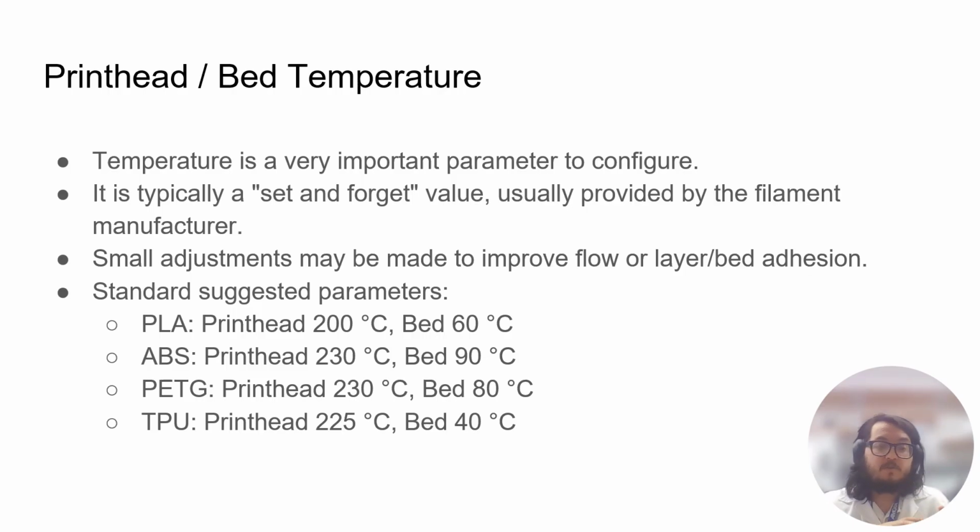The reason why we use those temperatures is that those are the temperatures where some of the amorphous polymers really are in this more flowable state. The more crystalline polymers are in this melt state, so the melting temperature. For the print bed temperature, we usually try to reach the glass transition temperature, which is where it becomes softer and they stop structuring of these crystals.